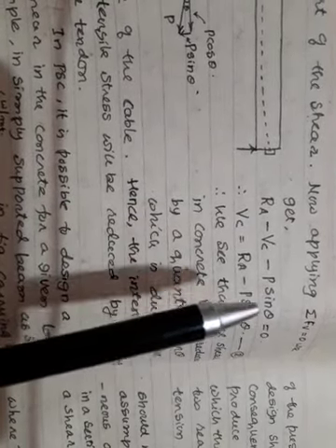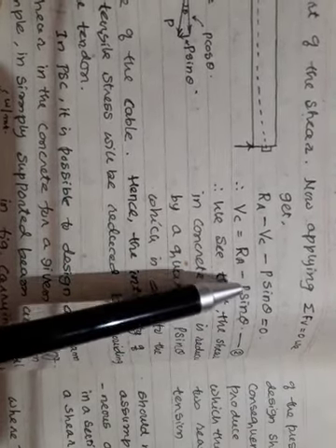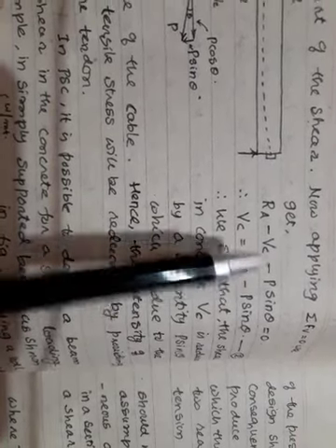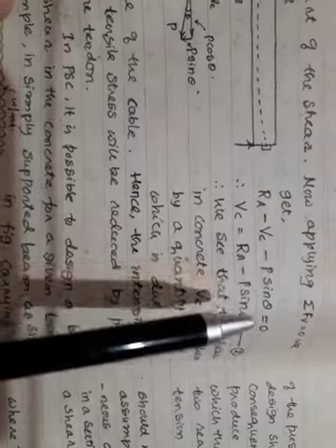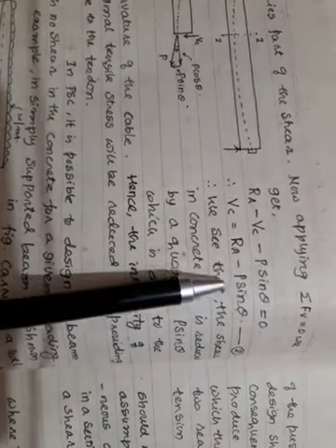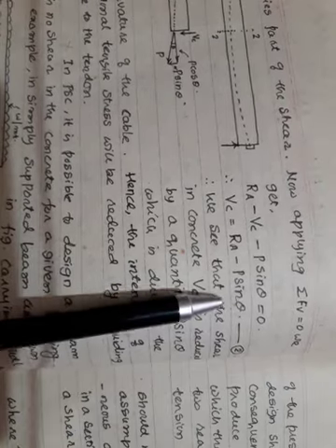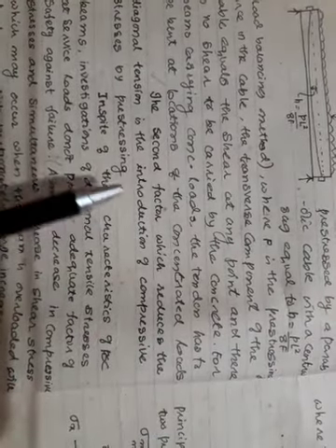In the sense, there is a possibility that when I go on increasing the value of P and theta, I may reach a stage wherein there is no shear force in this concrete at all. I can reach that stage also. That is the beauty of this prestressed concrete. Whenever you apply a prestressing force with some inclination, it is an advantage. So this is the first factor which is going to reduce the shear in case of your PSC beam.